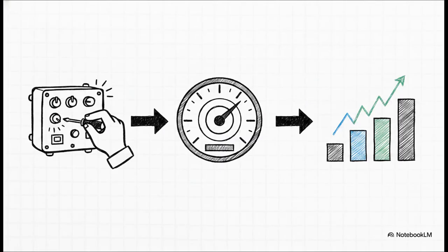If we extract the technician's exact testing procedure, it gives us this beautiful baseline setup. Before you even think about replacing any parts, you've got to calibrate the milliamp to PWM converter. You have to verify the ECM is programmed for a 3% speed droop, and make sure that both the ECM and the Woodward are targeting the exact same rated speed, which is 1200 RPM in this case. Then you compare the frequency output from the magnetic pickup unit to the controller.